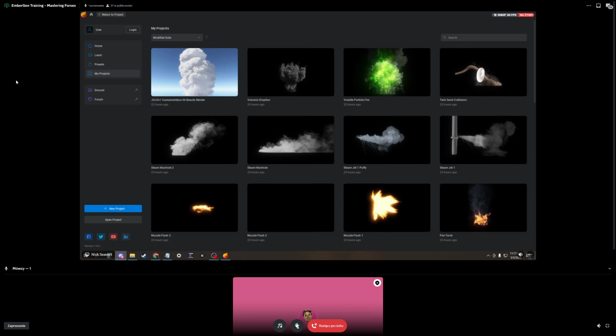And that is because in the particles, we have an active forces tab. And we're saying we want to take about 55 to 75% of the volume's force and apply that to the particles. But if I make the volume contribution 0, now our particles aren't going to be affected at all. If we make it 100%, it will follow 100% of the volume. And then you kind of have a range that you can say, hey, I want to follow the volume a bit and I don't. And so that gives you some randomization for each of your particles individually.